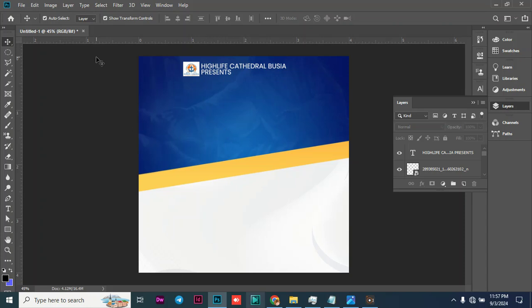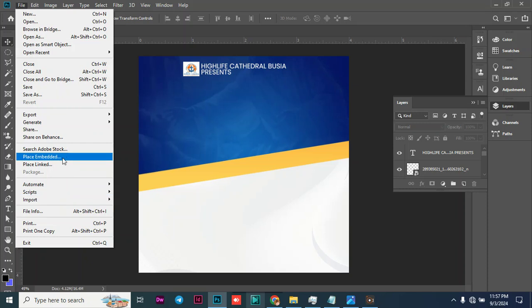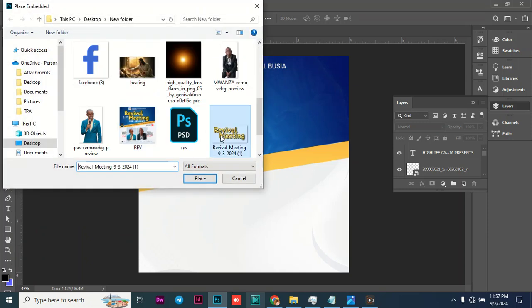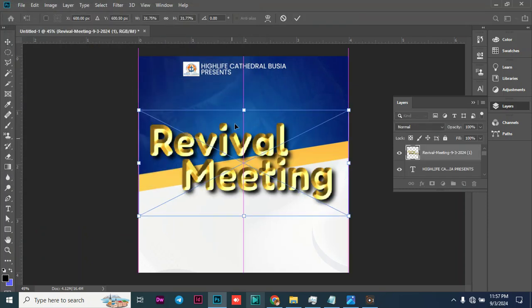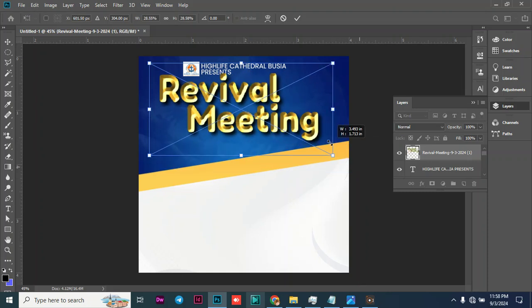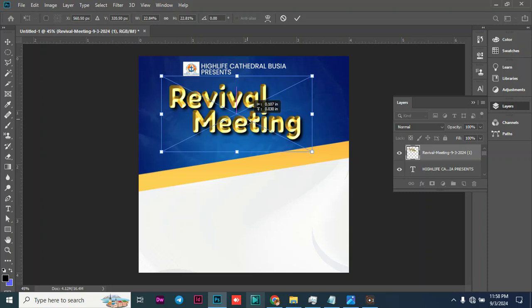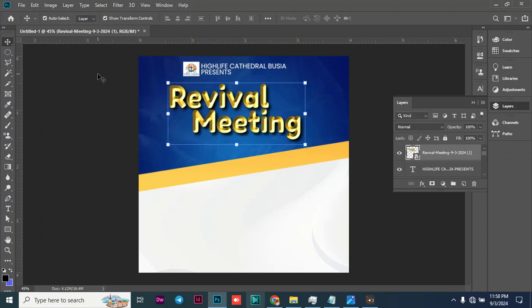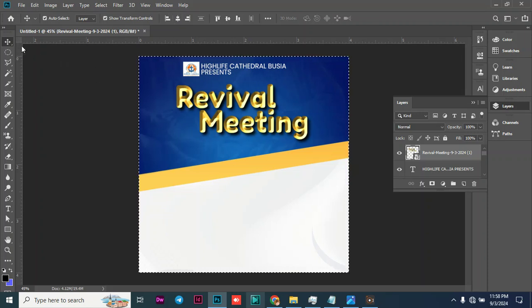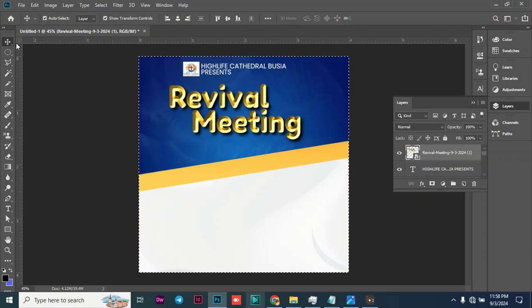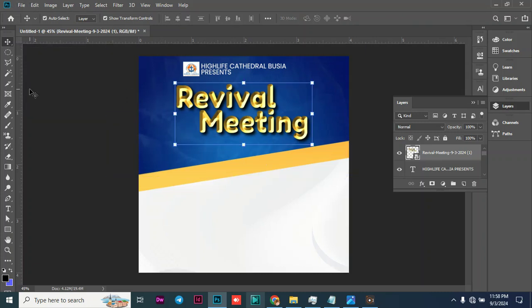Now that is done. The next thing to do is just to bring in my 3D title. So go to File, Place Embed, and then bring in the 3D title. So that is the 3D title I've just created. I want to reduce it so that it fits. So that is okay. Then make sure that this is also center aligned. So Control plus A, then click on center aligned. So the text is center aligned very well. Good. Now you have been able to bring in the text.